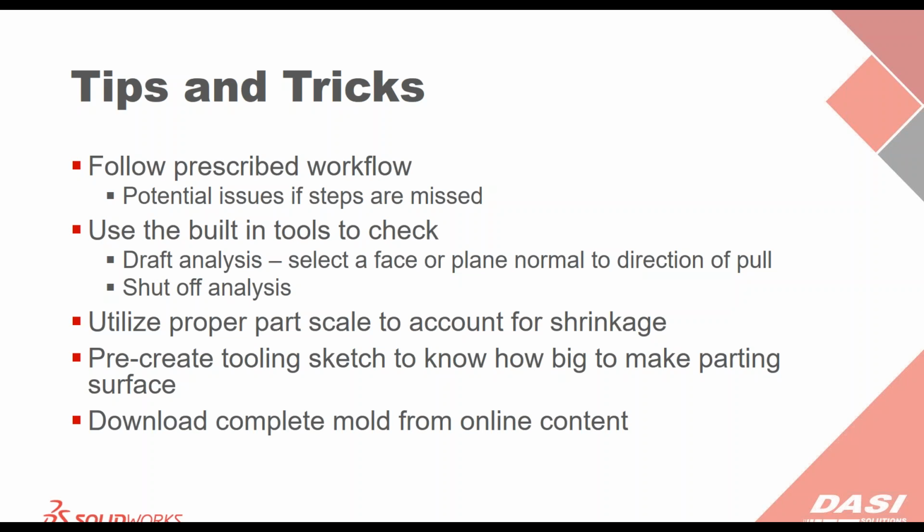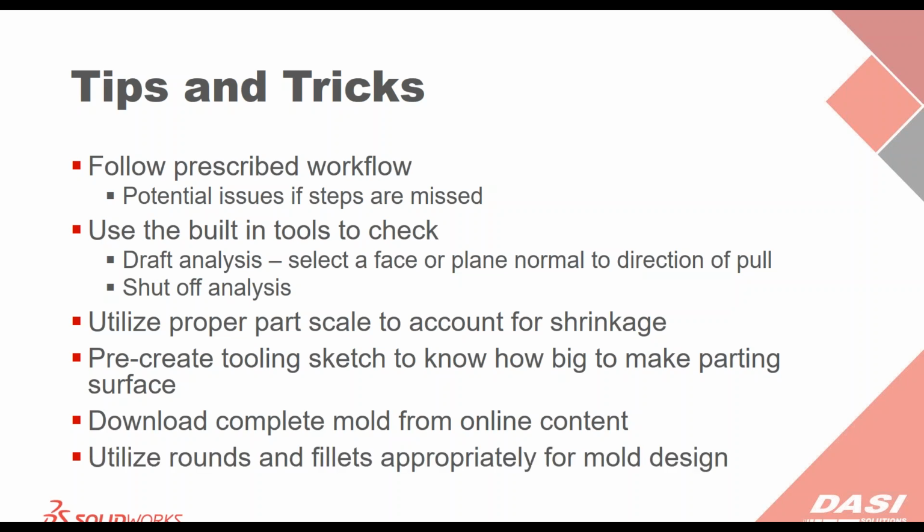And then of course you can download your complete mold from online content to save yourself time. You don't need to go ahead and model all that extra geometry and tooling. You can just customize that as you go and as needed, and then drop that into SOLIDWORKS, drop your cavity and core blocks in, and pretty much be done with it. Another quick reminder is to always utilize rounds and fillets appropriately for your mold design. This is pretty self-explanatory for machining, but make sure that you're rounding stuff and filleting stuff in your tools.